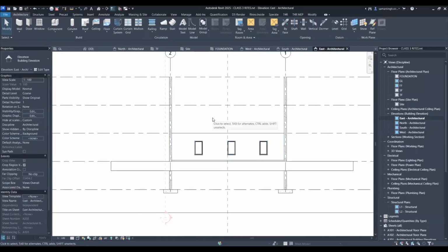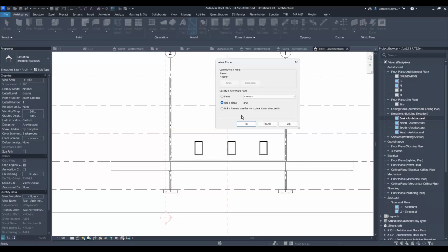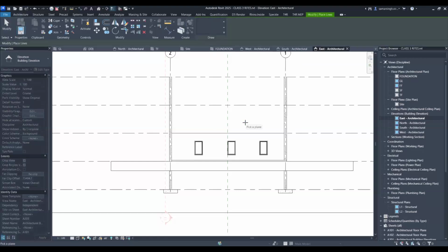There is one more very simple tool called model line which can be used. So this particular model line, you can see I have selected here. This is an architecture tab. This can be used to make whatever in your drawings, because once you are making a working drawing or designing and you are using multiple lines, model line will be your friend, which will be there as your working line. If you might remember your college time, when we used to do hand drafting, the lines that we erased, those lines can be replaced with model lines.